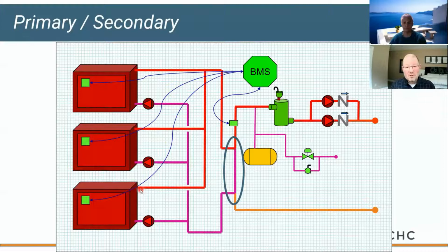You could take the discharge of this boiler and tee it right back into the system. Because remember, we typically have balance valves on each one of these boilers, and that allows us to dial in our flow rate based on piping length. So in general, you do not need reverse return with primary secondary. Now, we'll get to another scenario where reverse return is critical.